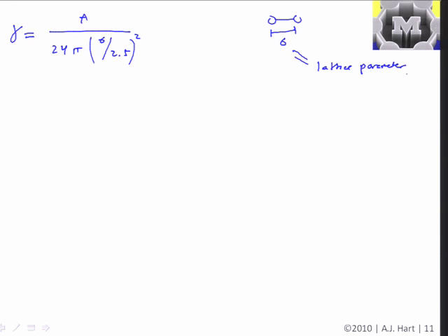I have a question. What's the difference between D naught then and sigma? It's just defined as sigma. Well, what the reading does is it boils it down to sigma divided by 2.5. So I was using a d0 just to be able to draw a parallelism to our simple separation model. And it's a characteristic dimension of the lattice due to the interaction between the atoms. So we can just note that the surface energies of metals are typically much, much higher.